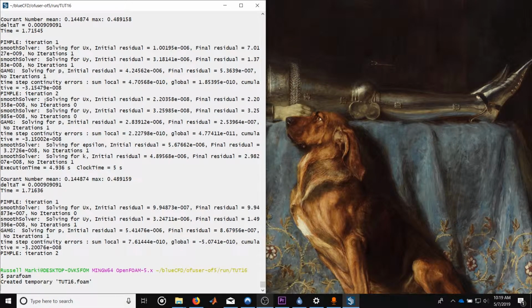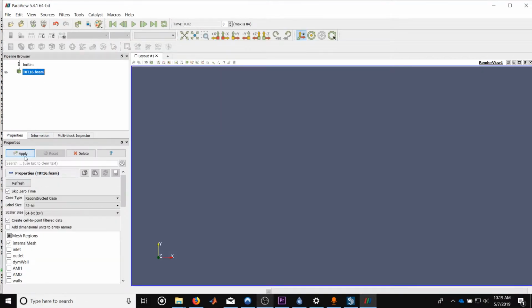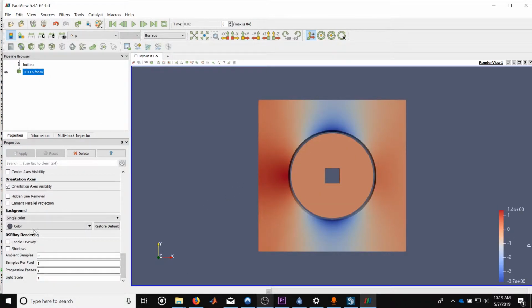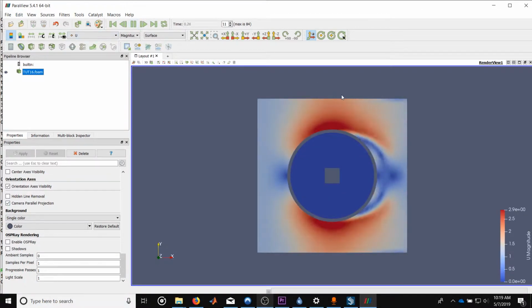What we just did here is ran the case, treating this boundary like it's a regular wall. You'll see now that it does follow around the proper pattern. This gap right here, no fluid flows across it. This is the first problem.